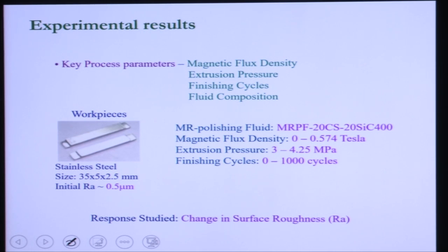These workpieces are made of stainless steel and are initially pre-ground. The initial workpiece surface roughness is 0.49 to 0.5 micron, so around 0.5 micron.